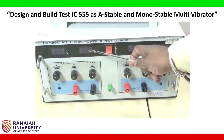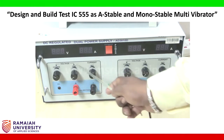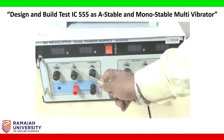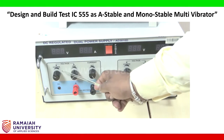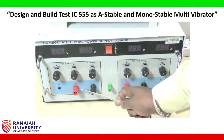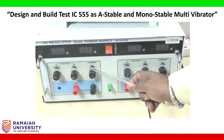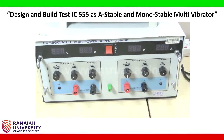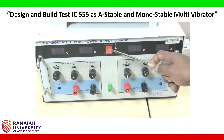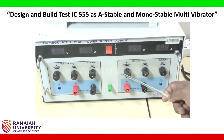This is a DC regulated dual power supply. In that we have voltage terminals and current terminals. These two terminals are used to set up the voltage. This is a coarse tune and this is a fine tune terminal. This is positive and this is negative. This is the current setting terminal. This is the switch to switch on the power for the DC dual power supply. Similarly, the same setup is on the other side.